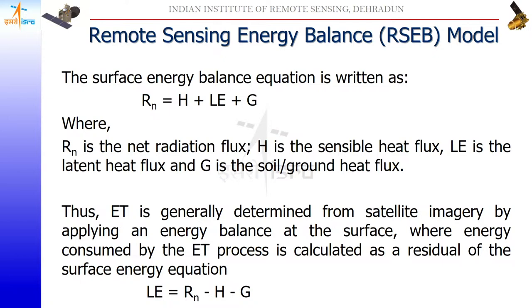Along with the crop coefficient approach, there is another approach which is most widely used, in contemporary with the crop coefficient method, which is also known as the remote sensing energy balance model. So what is the surface energy balance? Surface energy balance is basically a total integration of energies in the form of net radiation flux, which is ultimately fragmented into sensible heat flux, latent heat flux, and soil heat flux. So what are the different components?